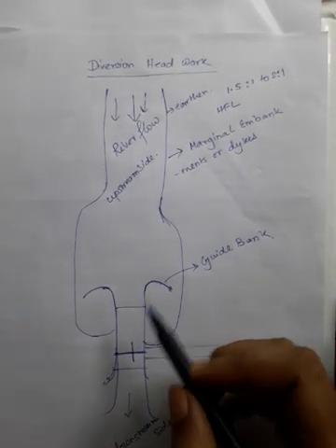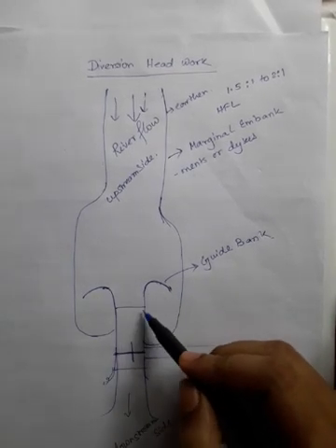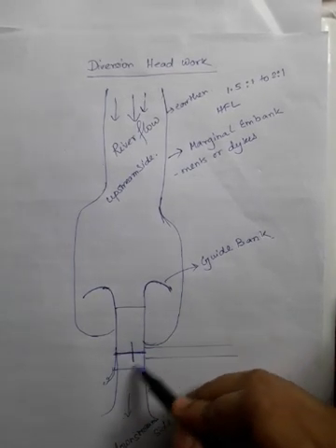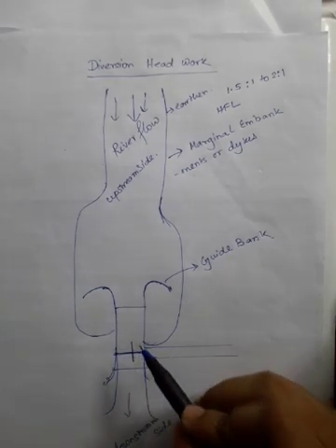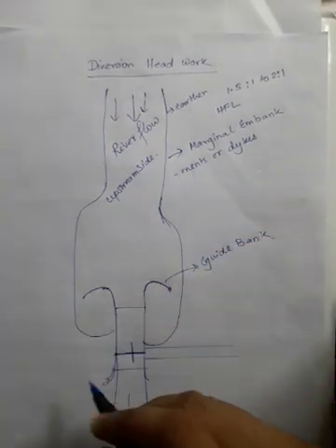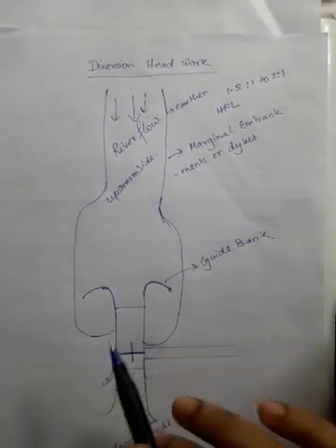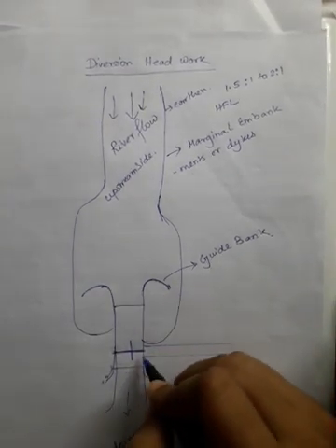So the purpose of this guide bank is that it protects the barrage from the effect of scouring and erosion. It controls the tendency of changing the course of the river, as I have said earlier. It controls the velocity of the flow near the structure here.